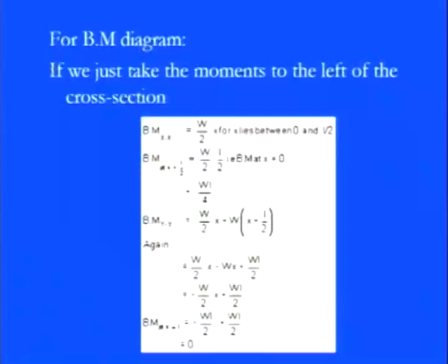For that we need to calculate the bending moment at the different sections. We have the simply supported beam with these two reactions, and at the midpoint we have the W. So, again we cut the XX section. First of all we would like to check the variation in the bending moment at the XX cross section. Starting from the reaction on the left hand corner, W by 2, if we go towards the middle portion, then the bending moment at the XX cross section is equal to